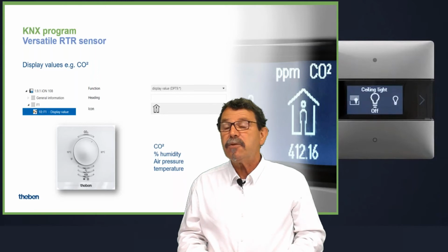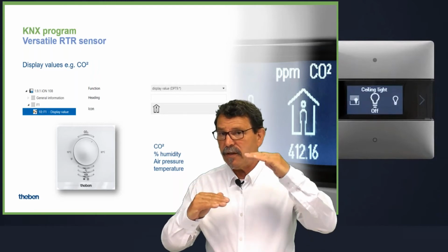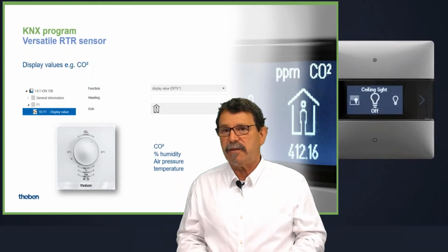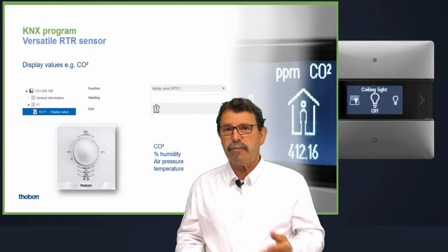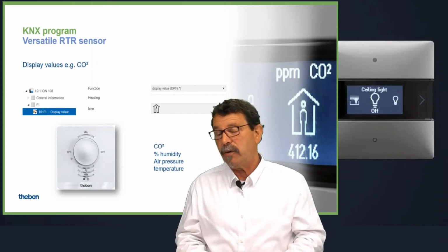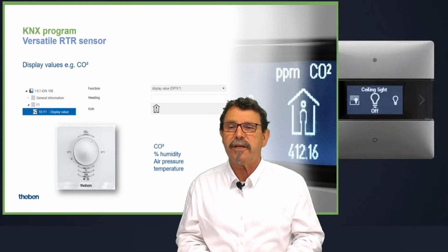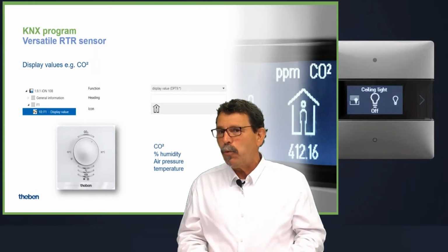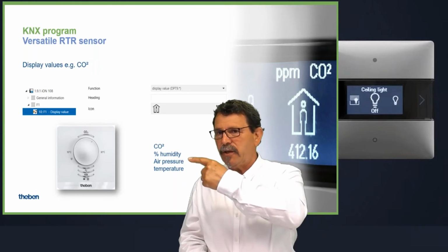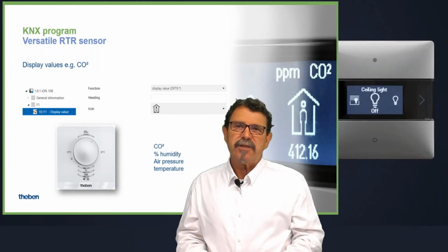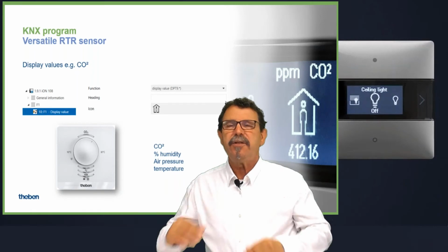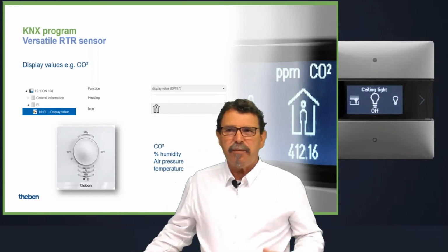So this is related to the air pressure, to the level above sea level. Due to that, the air pressure is different in Singapore in comparison to Germany, to Haigerloch, our city here where Teben is located. So we do the calibration internally when we know the air pressure, so we calibrate the CO2 as well, in order to get these measured values really precise.